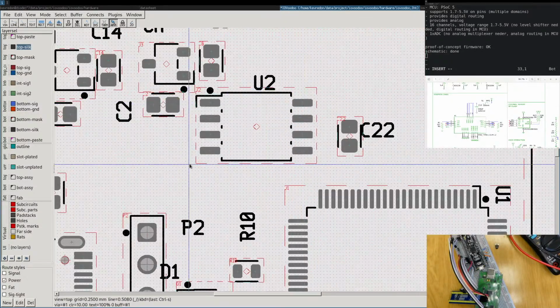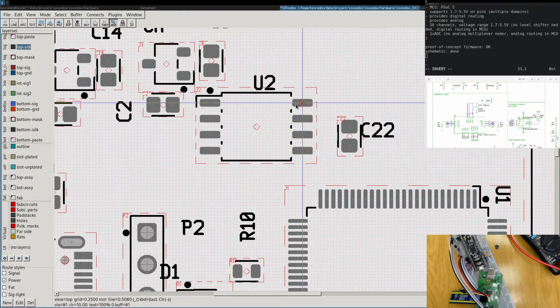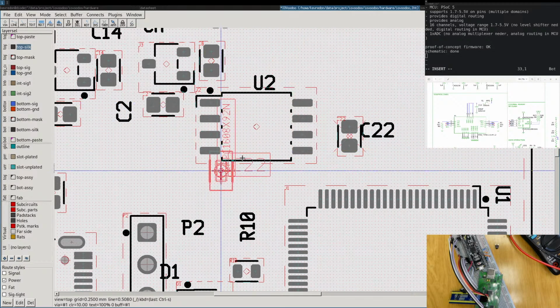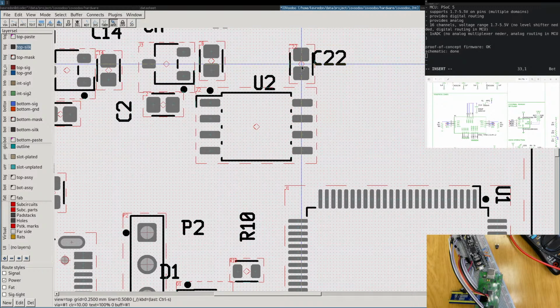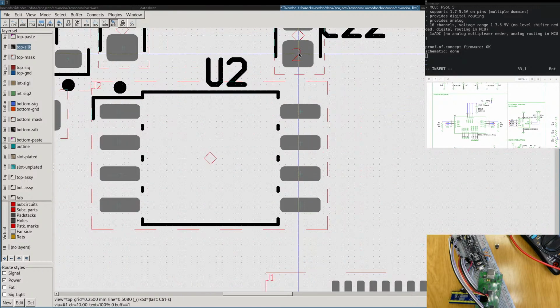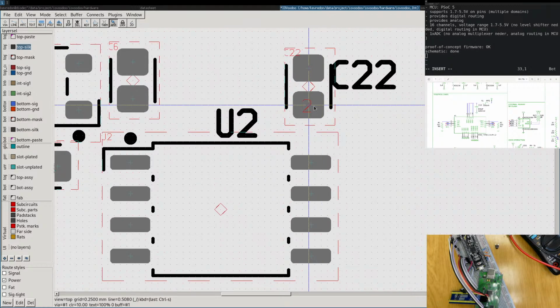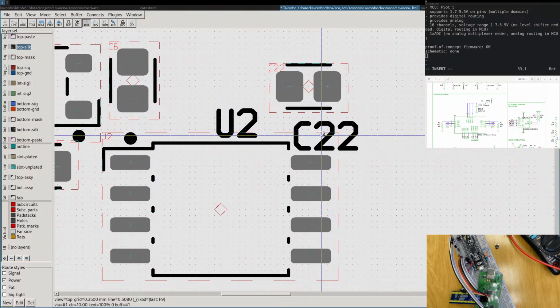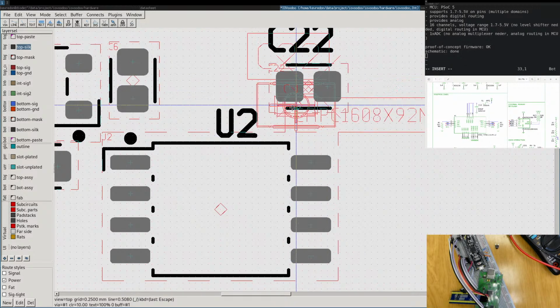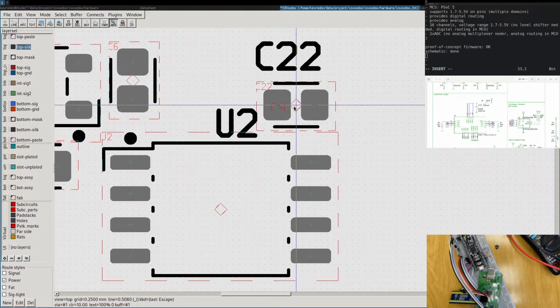So here, for example, the problem, I think this is VCC, this is wrong. Okay, that's the other way around. You cannot put them next to each other, you have to decide. We will put it next to VCC, and then there will be the ground pin. Have the decoupling capacitor next to VCC.